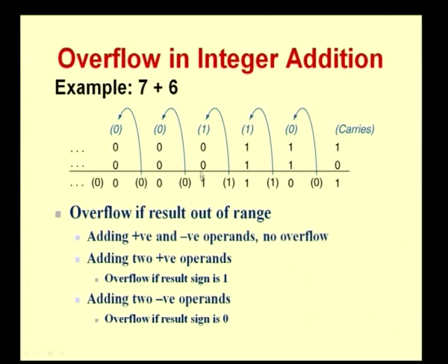Or looking at it another way, this is an integer, so it can be a signed integer. With the sign bit, let me assume 0 is my sign bit and 111 is the magnitude. So, 0 is the sign bit, 110 is the magnitude for the value 6. When I add these two numbers, you can see that the two operands have a sign value of 0, whereas the output produced has a value of 1101. The absolute value of 1101 we can see is 13, but the 1 here represents a sign bit. Therefore, this does not represent the value of 13. In this case, we can say that an overflow has occurred, because 13 with the sign bit cannot be accommodated within 4 bits. So, when my result is out of range and cannot be accommodated within the number of bits that I have, then I say that an overflow has occurred.